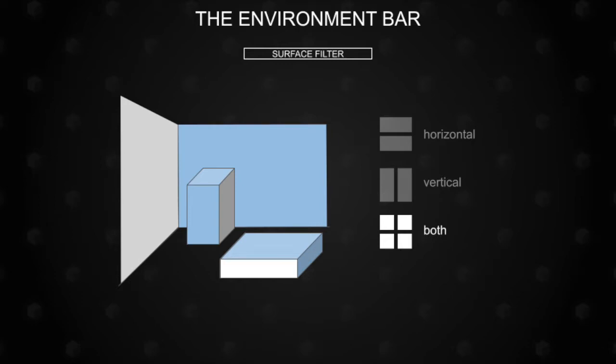Each of the filter values allows 1, 2, or 3 types of surfaces to be used as a support for the different models that you will place in the scene. Enabling the correct option can help you easily identify the surface you want to target in a complex environment by eliminating other surfaces that might be interfering. By default, the filter allows all surfaces. To keep only the horizontal surfaces, upwards and downwards, click the first option. Choose the second to use only vertical surfaces.